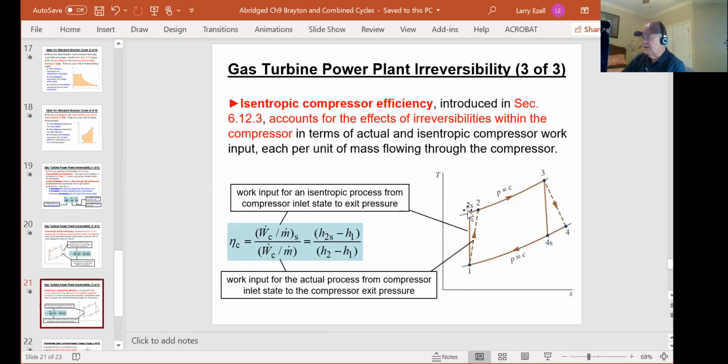And the value is a negative value indicating negative work, which is what a compressor requires. He switches these around to make them positive. I wouldn't do that. But now this guy's a lot smarter than I am, so you have to accept what he's done. But even though my equation I gave you had H1 minus H2s giving you a negative value on the numerator, it also had H1 minus H2 giving you a negative value on the denominator.